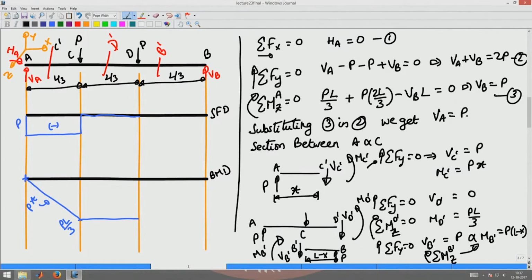So, this shear force is a positive shear force, because in the positive normal direction at B the shear force is acting vertically upwards, that is in the positive y direction for a positive x direction, which coincides with the normal direction of the cut at B. So, I will have the shear force going up now by P and remaining constant as P there.